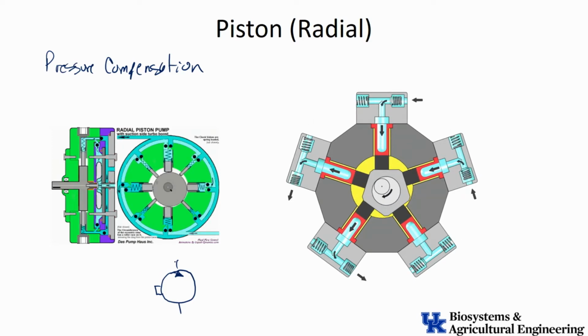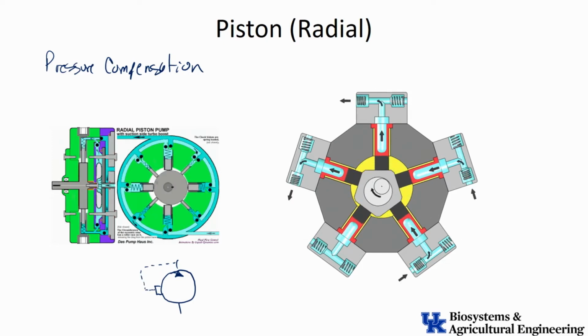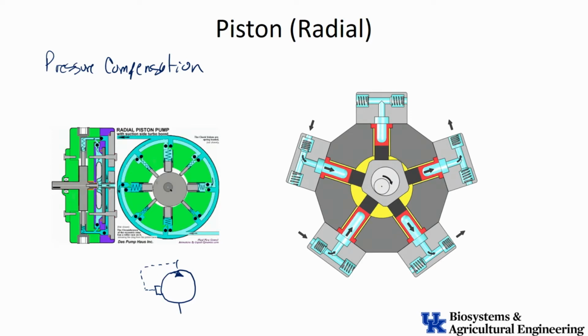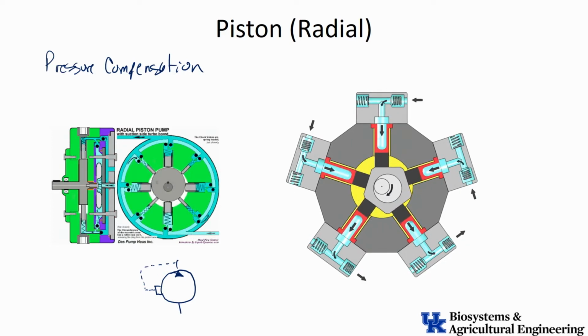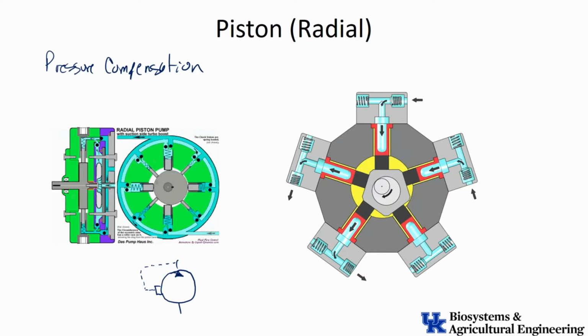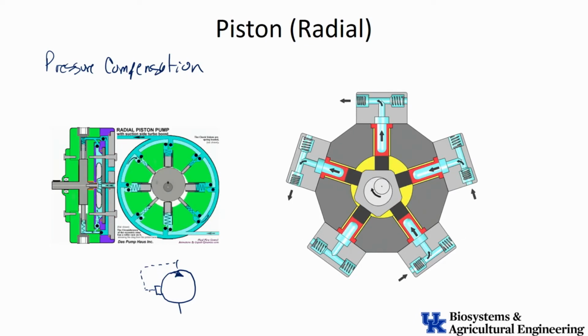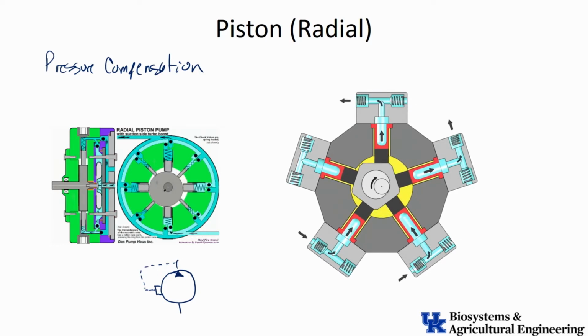Then often we will show a pump like this. And so what that's telling me, a dotted line, when I see a dotted line in fluid power, and pressure sensing, means that it's really small, it doesn't carry a lot of flow, its only purpose is so the side of that pump knows what the pressure is on the outlet of the pump.